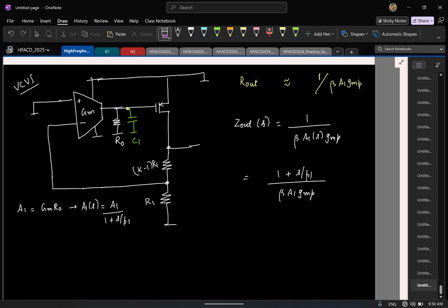Yeah, remember that anytime I have a voltage controlled voltage source, and if you have a delay in that feedback loop, we expect that there is going to be an inductive component, right? Yeah, this we saw, as he told, this we saw in common mode feedback. So this should not be surprising, because let us say you try to find the impedance here. Let us say you apply some test current, let us say for example.